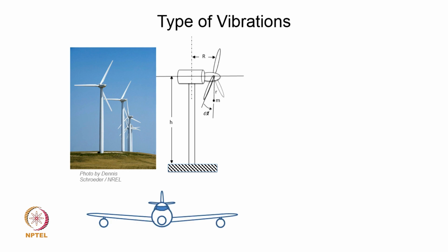So, this is what we are supposed to do when we are trying to explore different kinds of vibrations. So, another example is the wing of an aircraft. If we assume this to be rigid enough, then we can treat this to be a cantilever beam, obviously, right. So, you can have this wing as a cantilever beam, and this cantilever will undergo lateral vibrations based on either excitation from the flowing wind around it, or in addition you may also have excitation from the engine rotation. So, all of them will excite lateral vibrations.